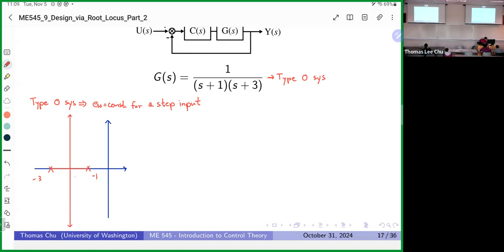Just from knowing that, we know this point here is -2, which is equal to the damping ratio multiplied by the natural frequency. Maybe I'll draw this out better. I'm going to say this is -2, and then this point here is your negative zeta times omega n.